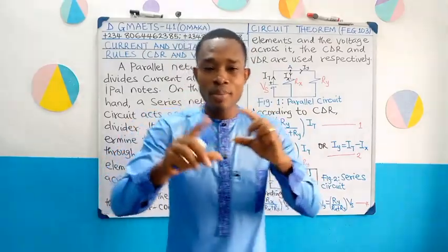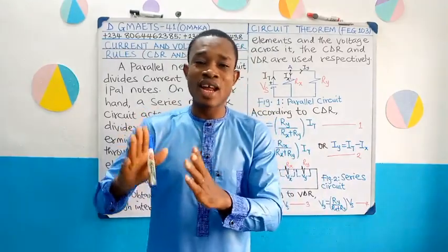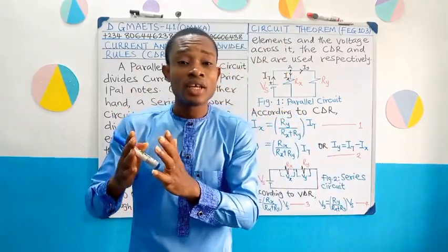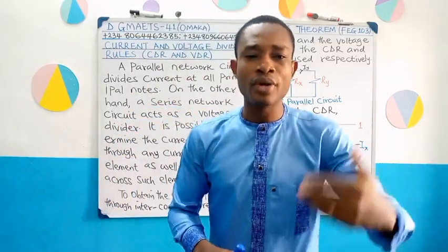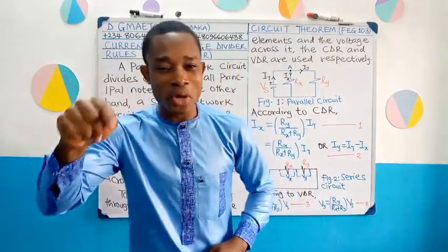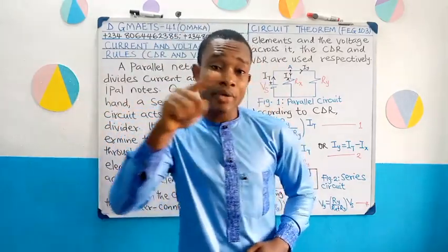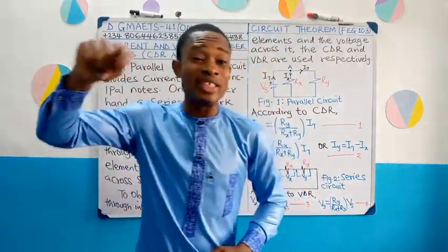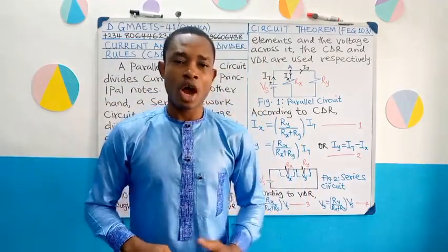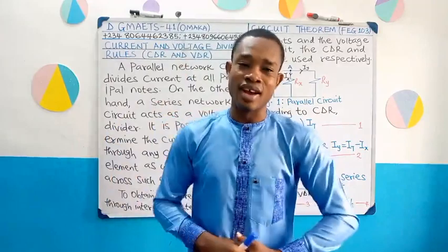And for us to be able to determine resistors that are arranged in series and resistors that are arranged in parallel in a given series parallel network arrangement, we have to know how current moves in such circuits. Knowing how current moves, knowing the point where current divides, I refer to that point as a principal node or a principal junction in that last class.